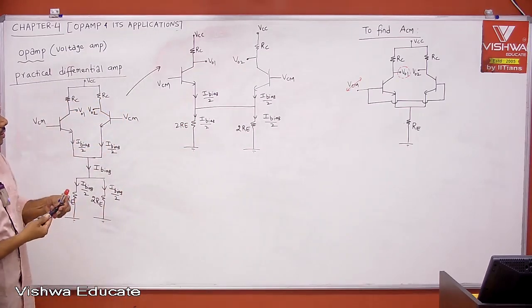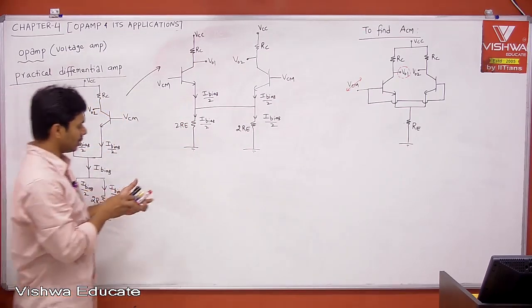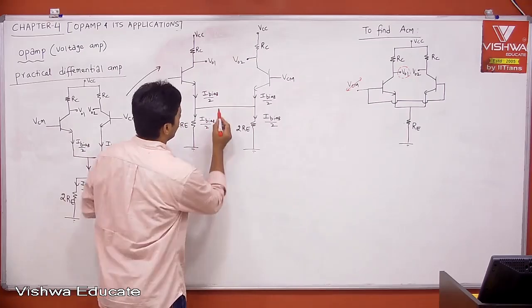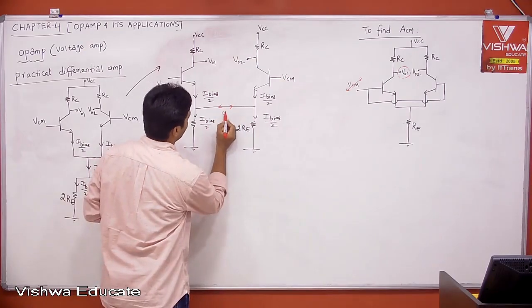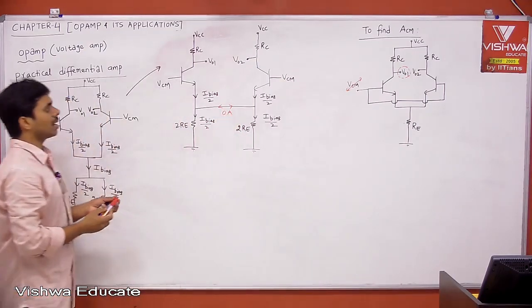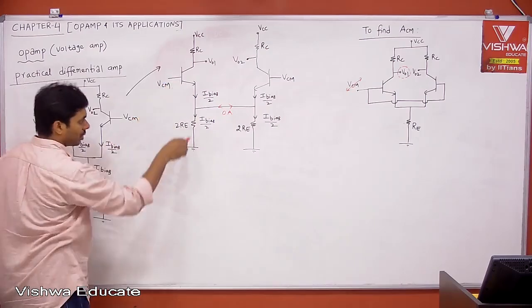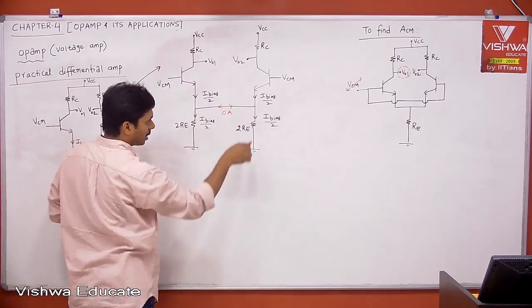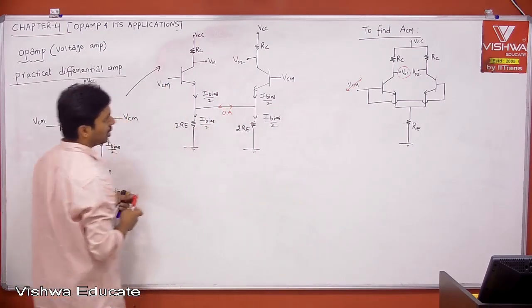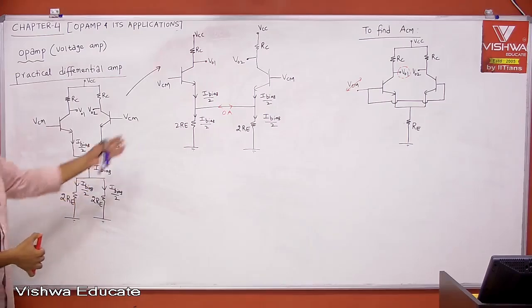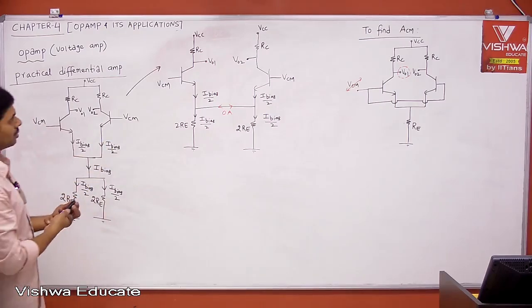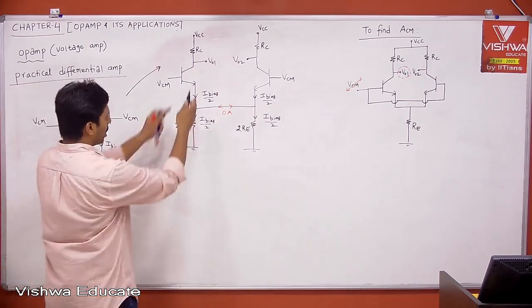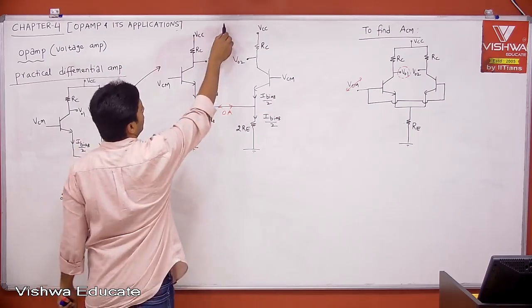If you take it out, because the current is 0, the current flowing through this is equal to 0 ampere. There is no current because the same current is flowing. In series, current is constant. KCL is satisfied and there is no current. If there is no current, both are the same. Then can I write this circuit as what? Now both are individual.